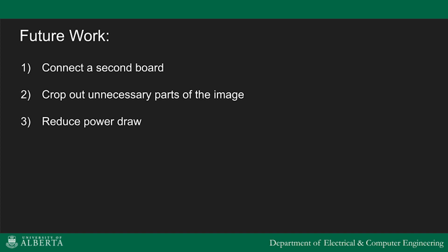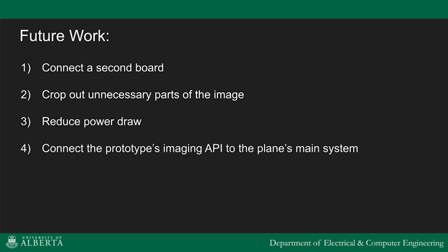One way to accomplish this would be to implement a sleep function on the second board so that it is put to sleep whenever the camera array isn't required. Lastly, in order to make the prototype function for the demo, we needed to cut out the Qt library that was utilized in the old system. So this means future work will be needed to connect our prototype API to the plane's main system.